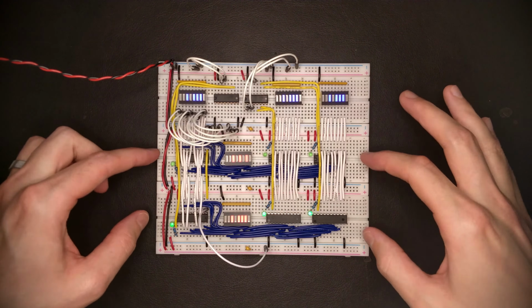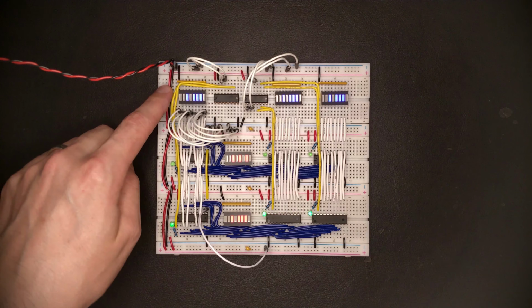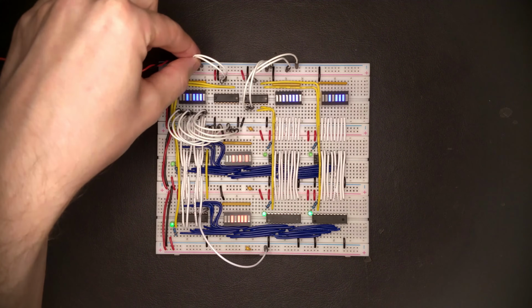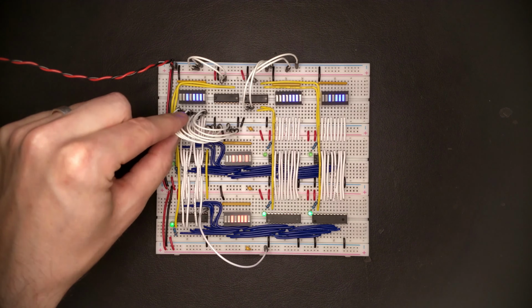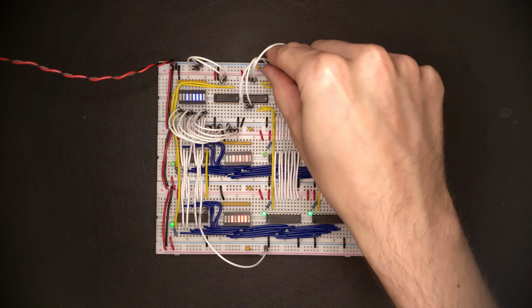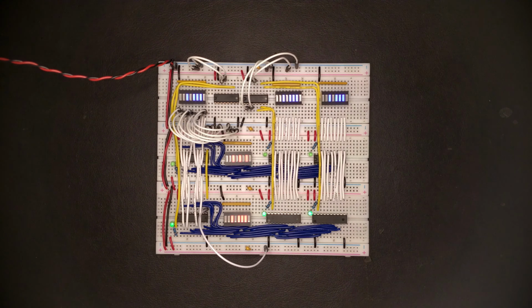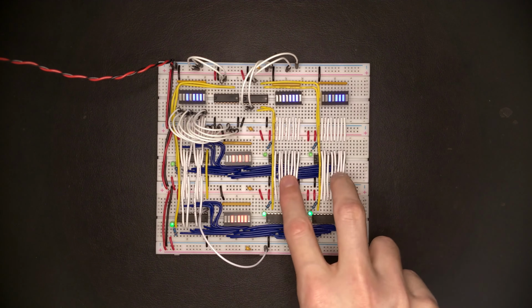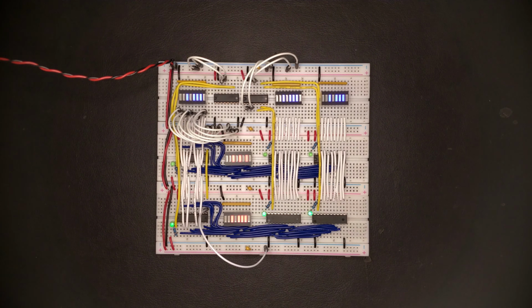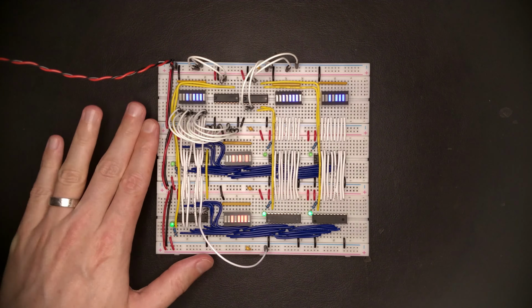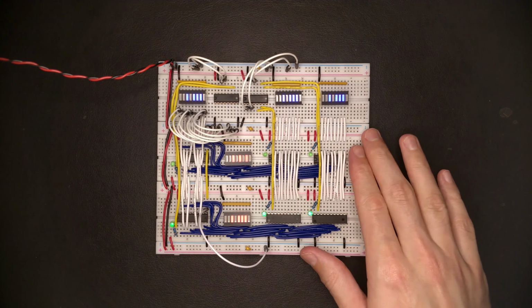All right, so I think with this, the first version of the register file is all complete. We have 2 registers, we have 1 write port and 2 read ports, and we have a corresponding write address input and write data input to perform writes into the register file. And we have 2 read addresses, with correspondingly 2 read data buses here that can actually read data out of the register file. And by picking these addresses here, we can choose which register we write and which register we read out.